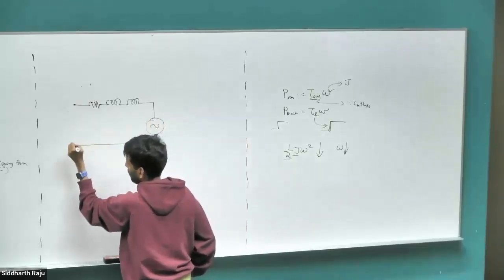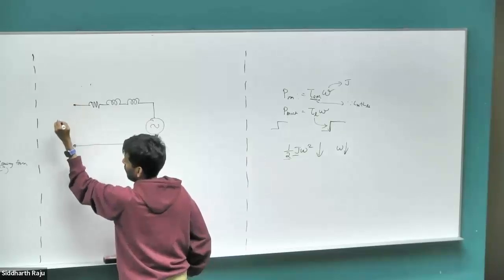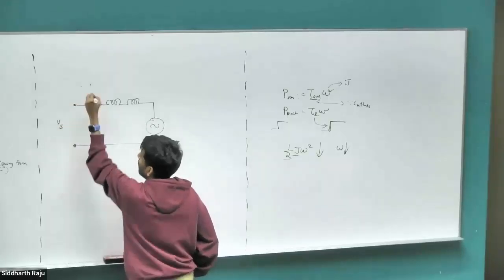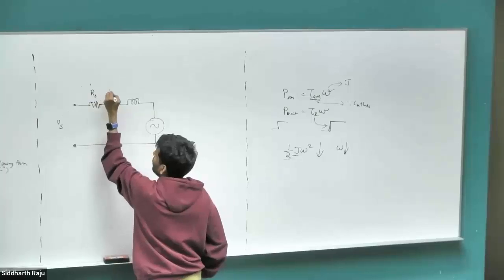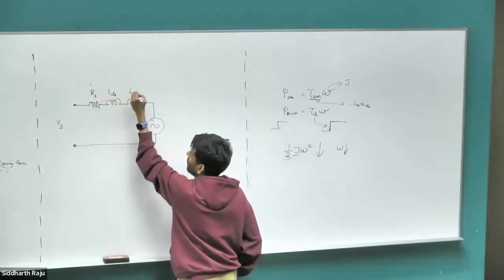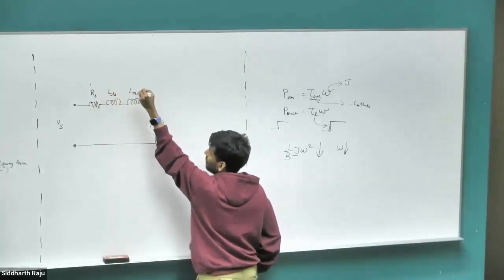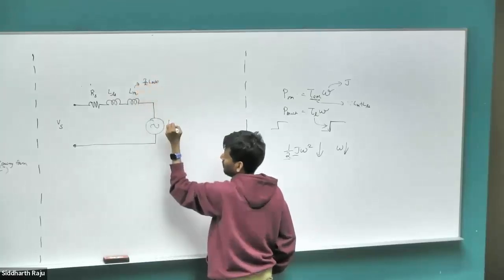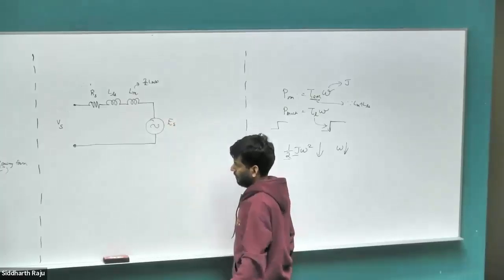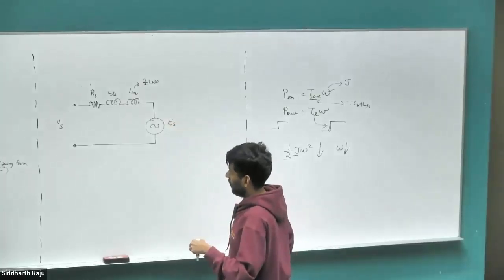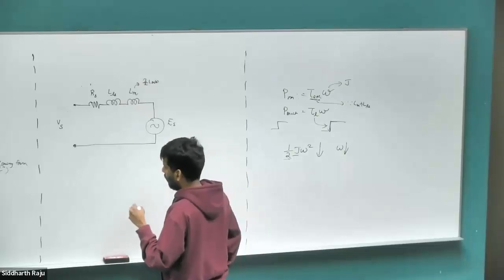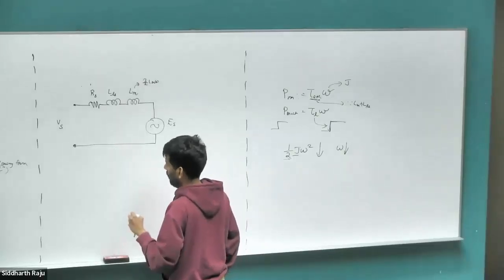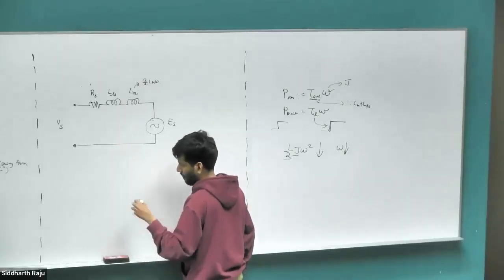So this is the per phase steady state equivalent circuit. You apply some terminal voltage, you have some stator resistance, you have some leakage inductance, you have some magnetizing inductance, which in itself is 3/2 times L. And then you have some back EMF that's created across the stator coil. Before we try and solve for this little bit of complicated circuit, let's simplify it a little bit further.